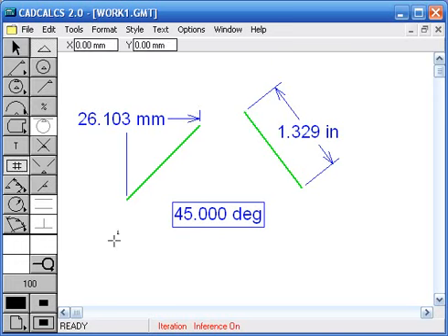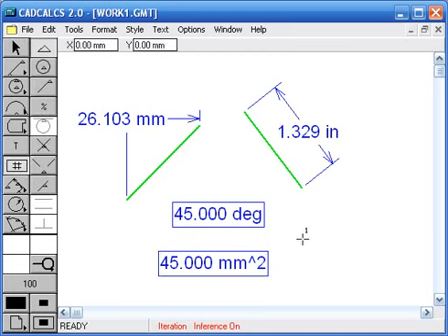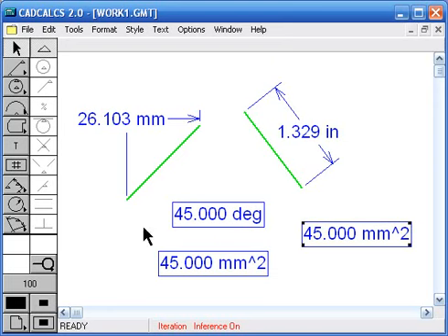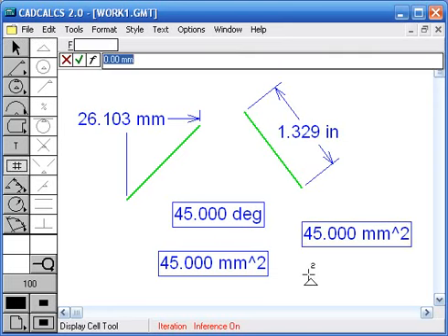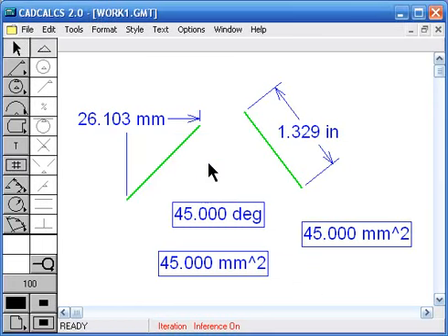So here is an example. Let's say I want an area to be 45 millimeter square. I have to enter it like this, to the power of 2. I can also enter it as 45 millimeter, but if I enter 45 millimeter, it will shout at me because it thinks that's a variable that it doesn't understand. And you notice the bug icon here telling me that it's incorrect.